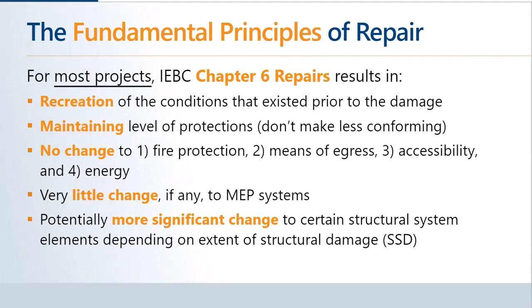Very little change, if any, to the MEP systems. Depending on the extent of work and what we're doing, those particular codes will have their own provisions, but from an IEBC perspective, it does not have additional work. And we just keep in mind that we might have more significant change to the structural aspects of our building if the damage triggers the SSD threshold.